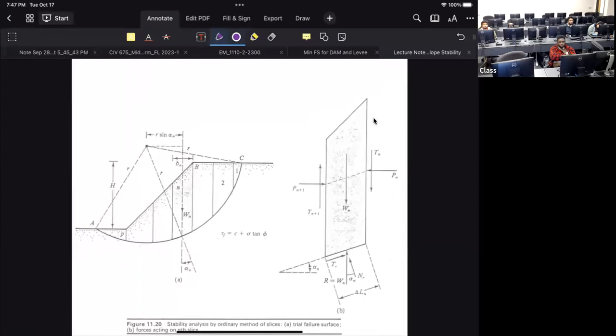Now we want to identify the load distribution within the slip surface, and we also need to find out the interaction happening there. How do we know if the slope is stable or not? We need to find out what force is acting on the slope to cause the failure, and you also have to know what resistance from the soil is there to keep it in place. So technically we can define the factor of safety.